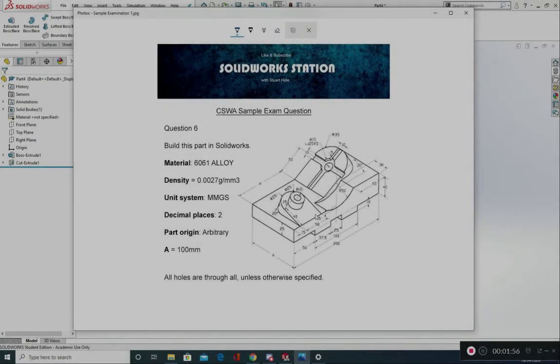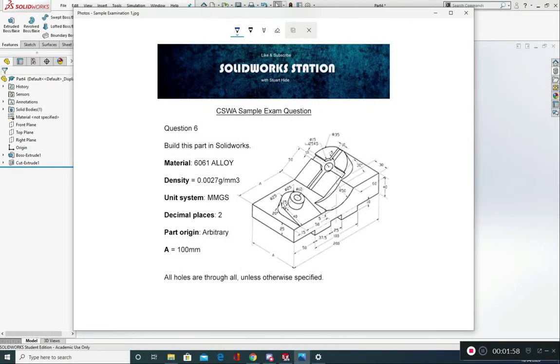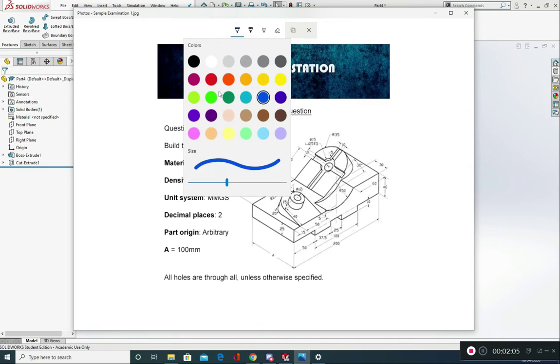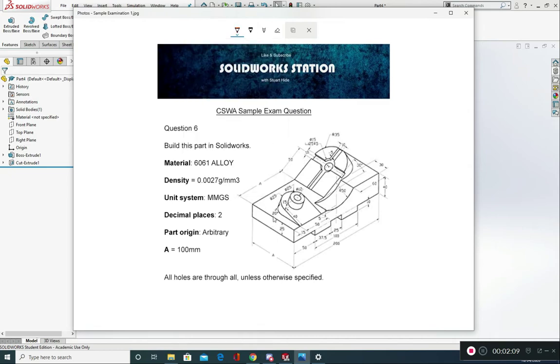Okay, so for the next bit, what we're going to concentrate on, if I just bring up my drawing again, is this particular feature that we've got here. Now, this has been drawn at a bit of an angle. I'll just indicate that to you in red. This angle here is of a lot of importance. We're going to have to create a new bit of reference geometry, which will come in the form of a new plane at 20 degrees to this line here, this top plane.